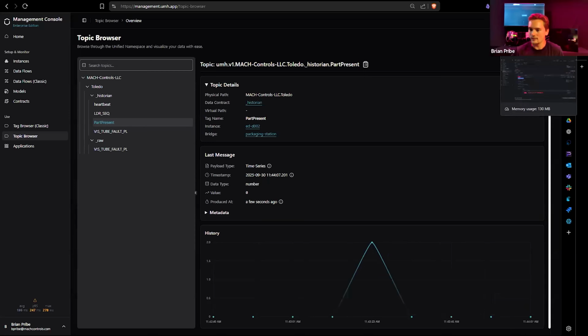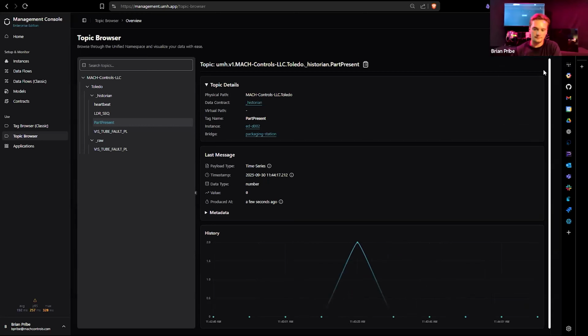Therefore, this if statement inside the protocol converter is really good. You map based on the incoming value of the Modbus device, and then switch case based on whatever you get out there. Perhaps 0 means door closed, 2 means door opened, 4 means whatever. So then you can go case by case and map that to a logical, actionable data point.